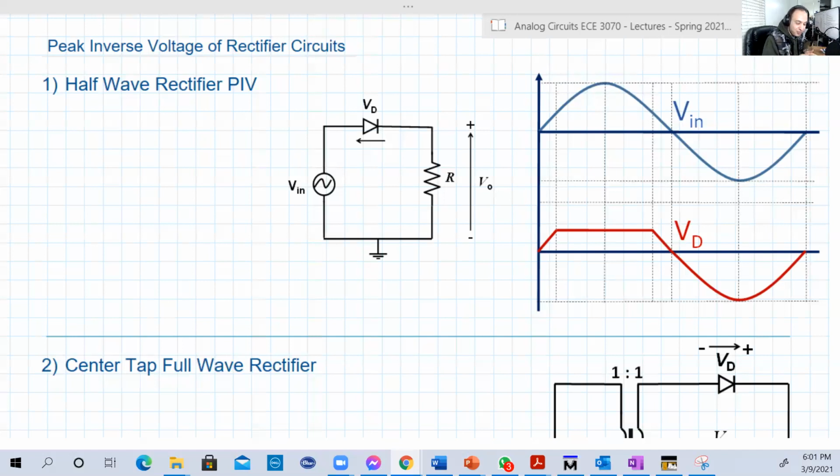In such kind of applications, the rectifier application, whenever the diode is reverse, it should stay reverse and off all the time until it becomes on again when it becomes forward. Okay, and breakdown is not desirable at all. So we must buy a diode with high breakdown voltage, but how high?